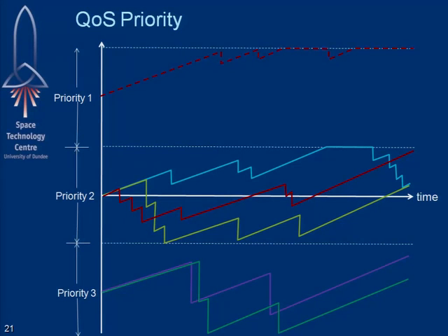And finally, where we've gone up here with the flat peak, this is somebody who hasn't actually used up their bandwidth. So they're actually underutilizing the link. So in this case, we might want to report that, but it's not actually that critical. It's not like a babbling idiot. So we can do this by periodically just polling to see if somebody's stayed at this limit for a period of time. So maybe every millisecond or so, we might just check to see if somebody's stayed there for a few milliseconds.